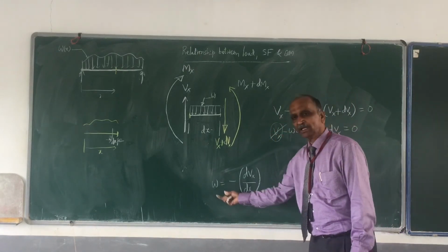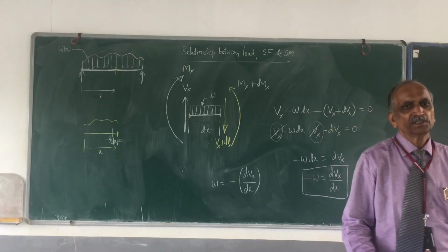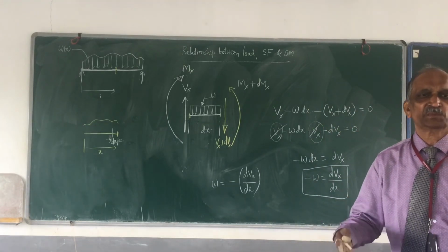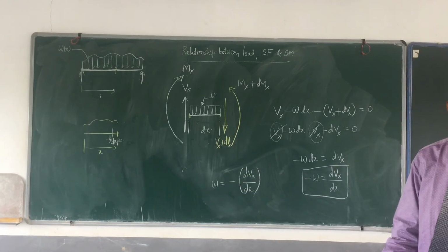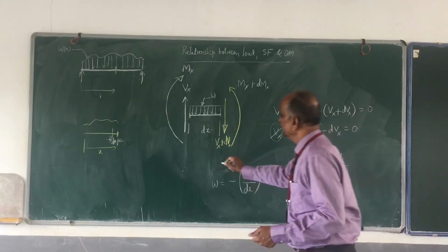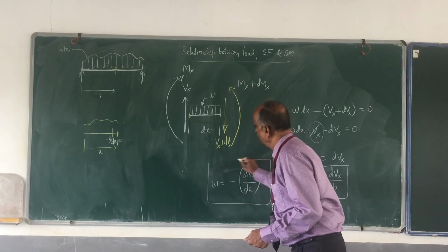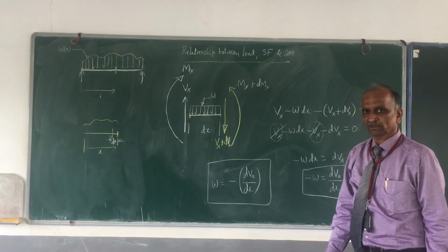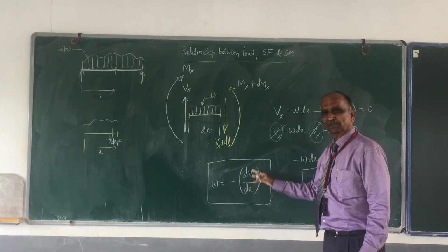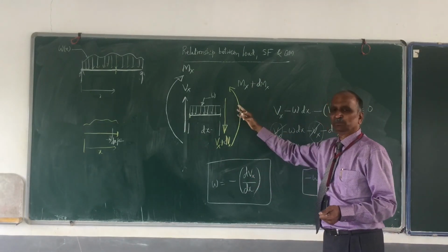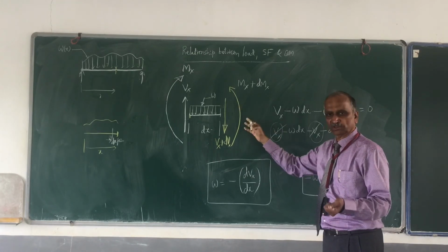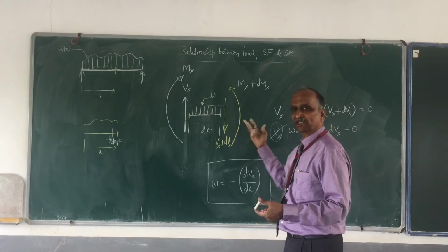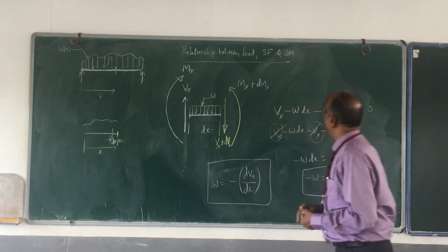That means the load at a section is the rate of change of shear force with respect to the length. So this is what we call the relationship between the load and shear force. When I apply the equilibrium condition for forces, this is what I get. Then if you take moment now, then if you take the moment,